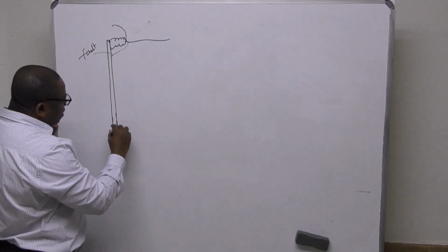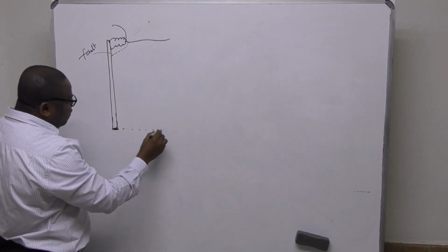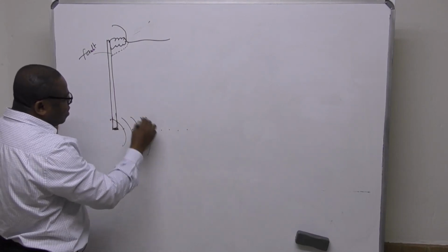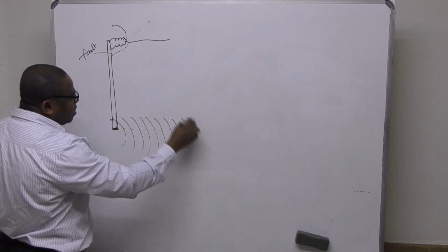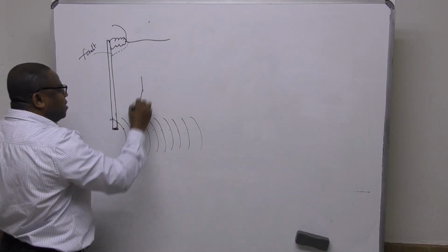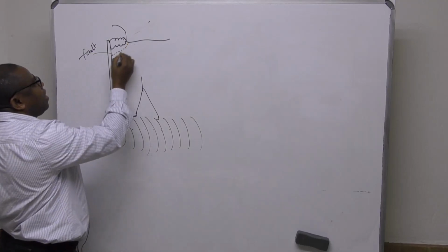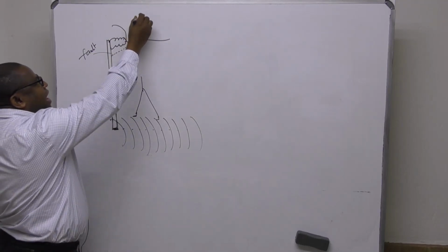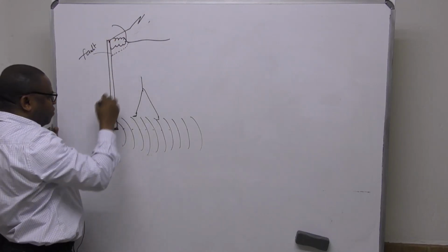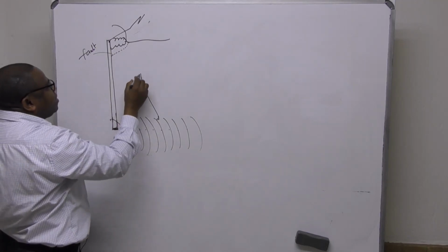So in other words, if I know the potential at this point, and at that point, as you go further away from this, the potential decreases. So let's say you have, just to represent this as a potential difference between one point and the other. Now, if someone happens to stand here like that, when this live wire touches that, or when lightning strikes this pole, current flows to the ground, and someone is standing here and is touching this.